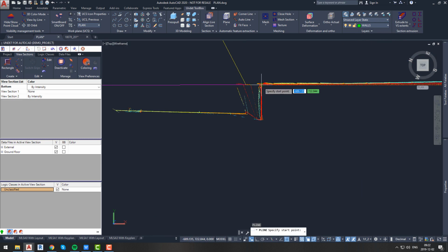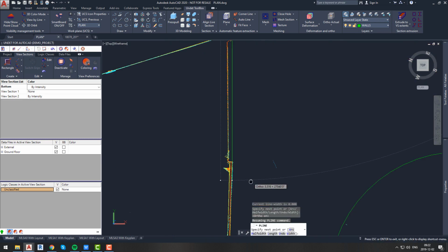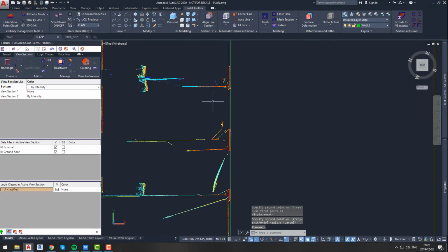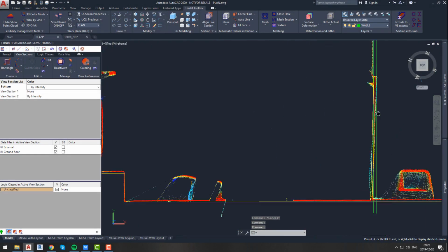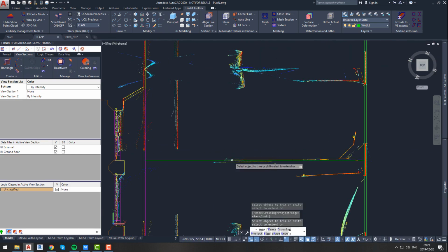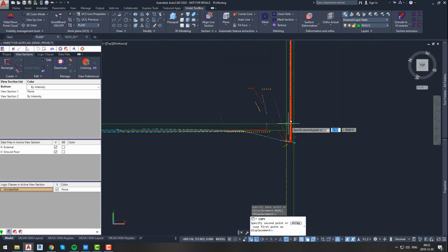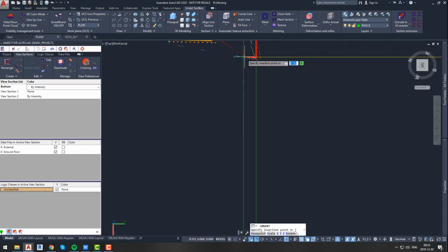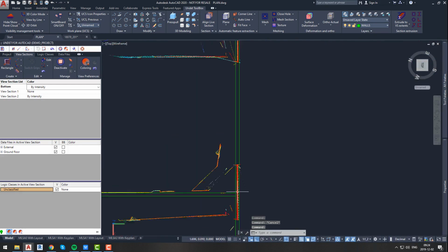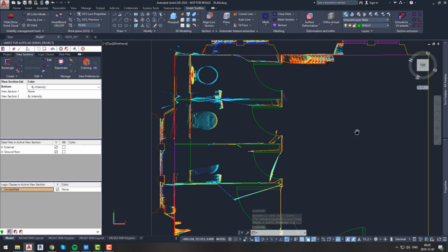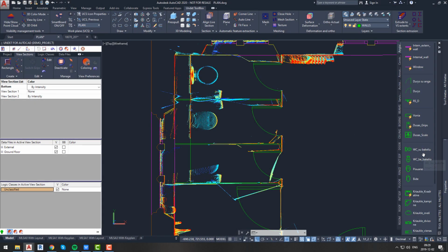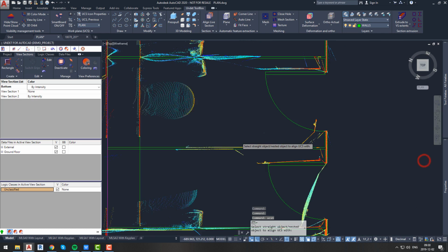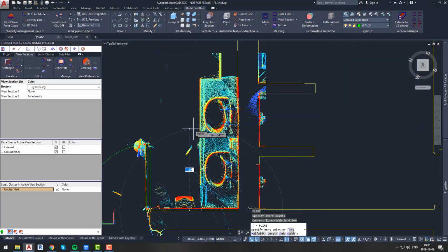Moving forward, we will start working with our floor objects. It will contain internal walls that are not structural, bathroom objects, furniture, stairs and so on. We will start working from this room, that seems to be a bathroom. After adding walls, we will add doors as well. To add objects such as urinal, sink and water closet, once again, we will use our dynamic blocks. And again, you can see how easy it is to adjust block dimensions and how much time those blocks save.